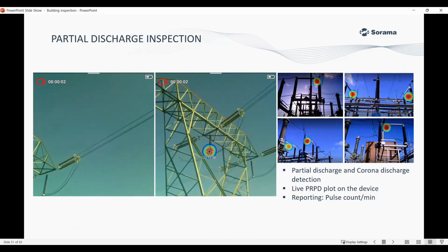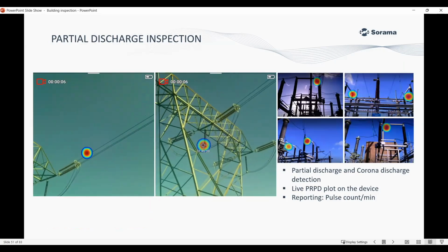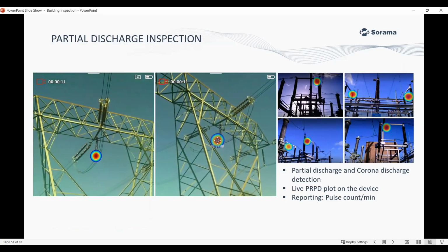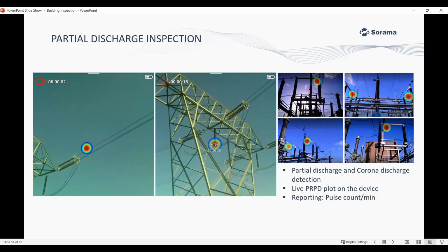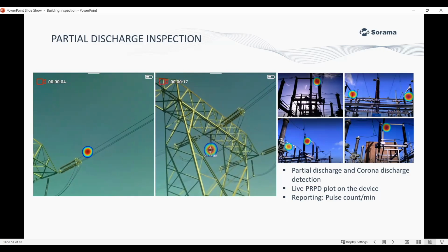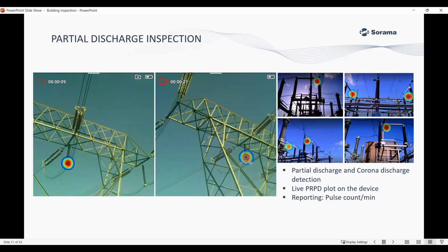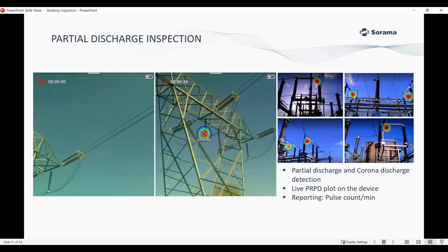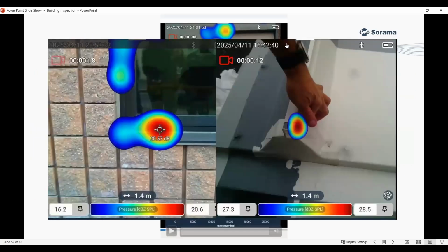Another application is to test high voltage systems, especially when you have insulation issues around high voltage systems, and that also creates high frequency sounds that people cannot hear. Sometimes, if you have noticed when you pass by an electrical system and you hear this buzzing sound, that can also be an indication of a failure. And this actually summarizes what I wanted to share with you today.